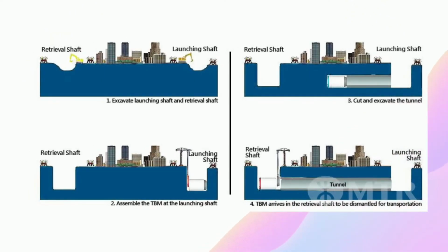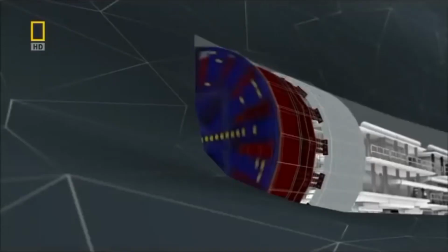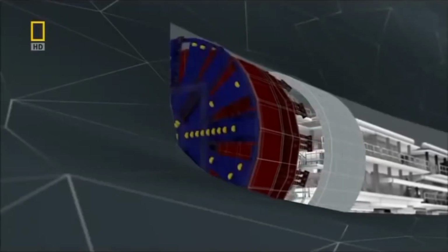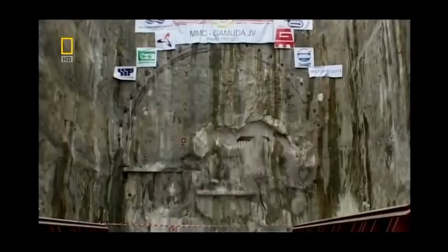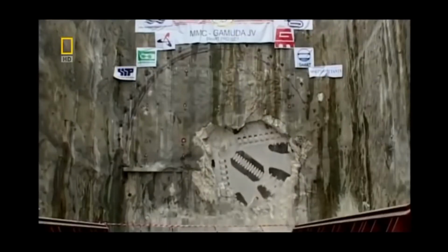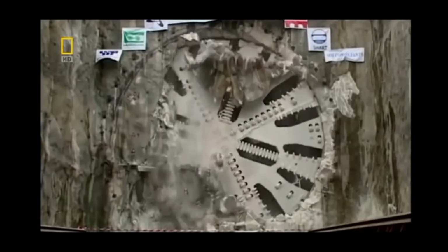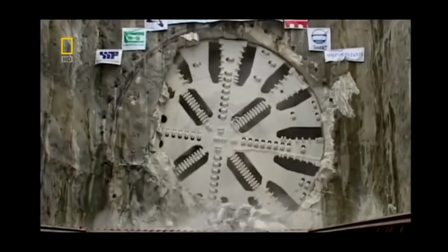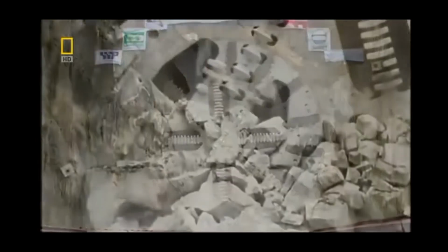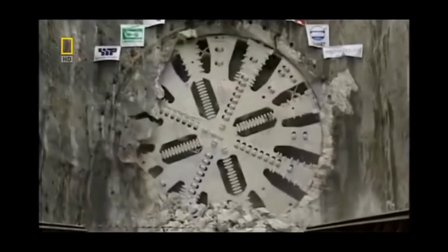This is the image of the TBM construction process. Moving on to the details on how TBM is passing through the soil. Firstly, the cutter head, which employs these cutters and sits at the very front of the TBM, does the majority of the hard work by rotating and digging away at the dirt to allow the machine to go forward, and is made up of hundreds of steel blades that chip away at the soil ahead as it spins.